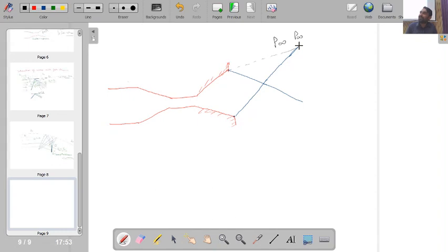So where pressure has become P infinity, there this shock wave will now reflect with the free boundary, because up to this point pressure is different, but just after this point pressure is free stream pressure. So now after this, the wave cannot propagate because pressure is the same. If a wave is there, then pressure has to be different on the two sides of the wave, but sufficiently far away we will be finding that pressure is actually equal to free stream. So I can say that this is the free stream boundary at which my wave is interacting with the free boundary.